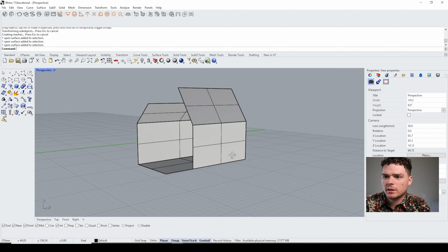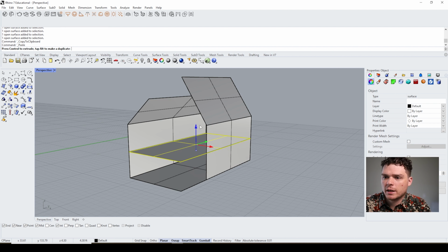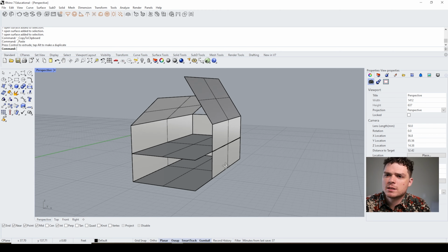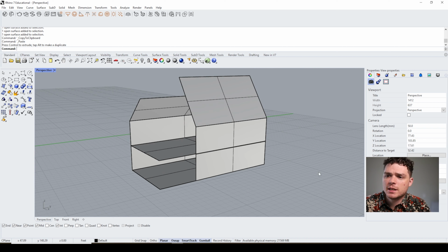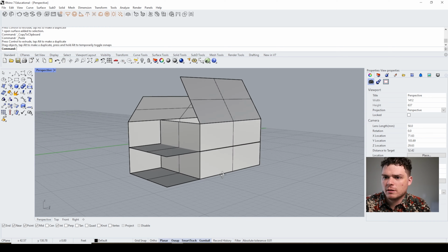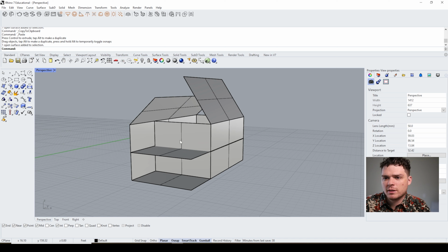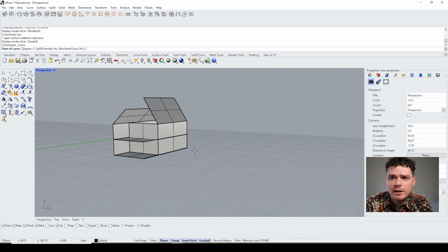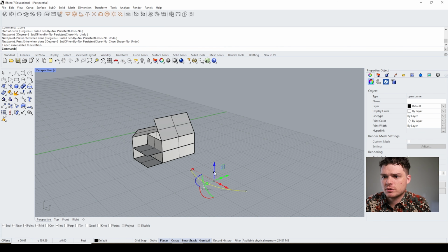And you can see very quickly you can get some pretty conceptual massing, little kind of napkin sketch ideas about, okay, I'm gonna have this indoor-outdoor space. Maybe it's protected in one area, but here it's not. I can go Control Shift, Control V, and I can maybe define a kind of front porch that's protected. Maybe in my head I'm already thinking that this is gonna kind of become like a trellis. And this doesn't have to happen for like a tiny house. Like you can very easily do this as a tower just by extruding geometry.